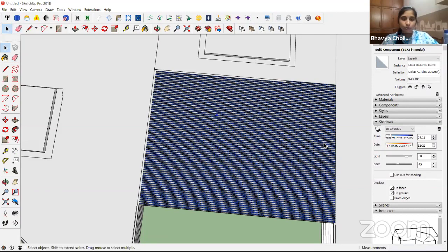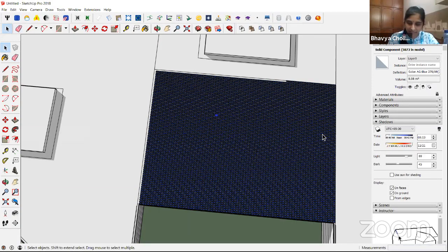Now let's say this is 290 watt peak, for example. That means 290 multiplied by 5873 is approximately 1.7 megawatt, the capacity of the solar plant that can be installed in that area. Considering this, you're working with the complete area. Now, how did I decide based upon it? I'll take the erase model option and start erasing a row or two rows of it, like this.